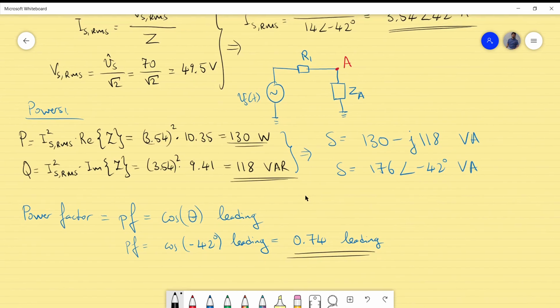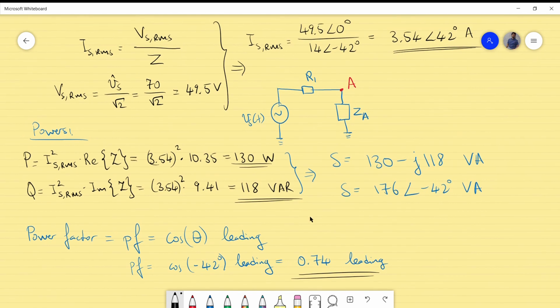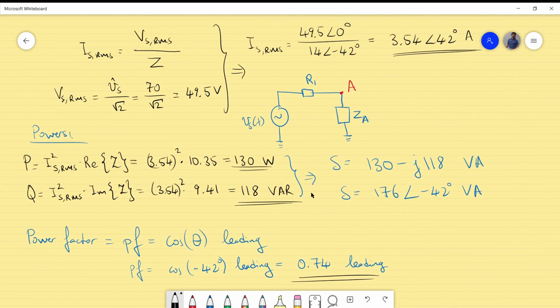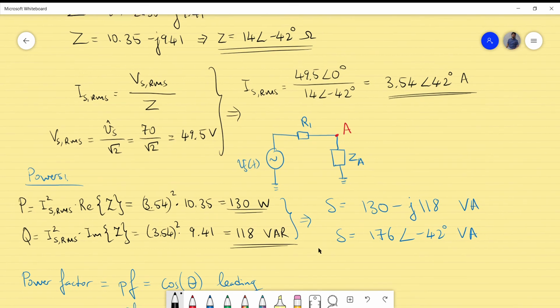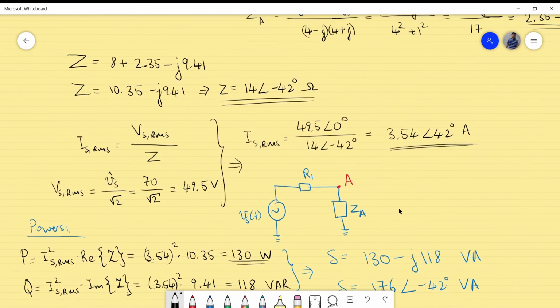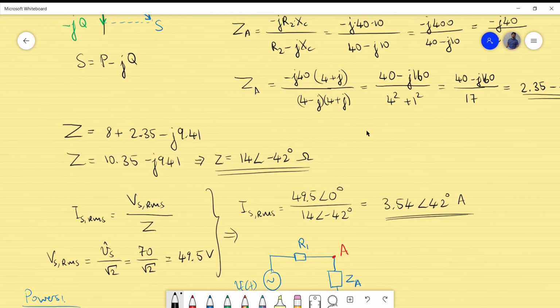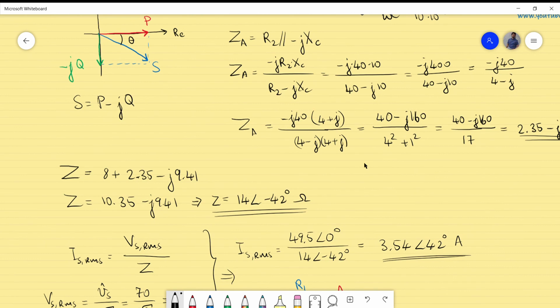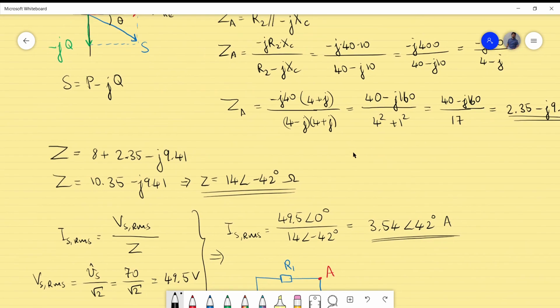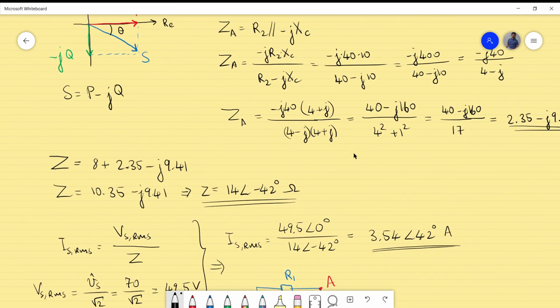Okay, this is a little bit complicated circuit because we have a parallel combination and a series combination of 3 components, so that will require also some extra work if you compare this, for example, with example number 2, where we had only one capacitor and one resistor, but the procedure is exactly the same. You follow the procedure of the complete total impedance, you calculate the total current.